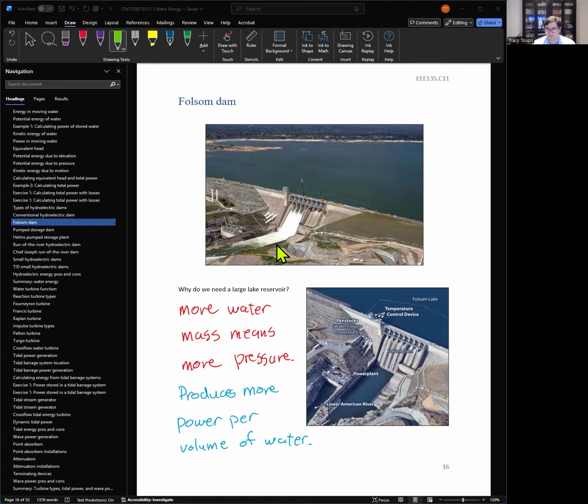Other thing you should note is the distance, the height. The after bay is down here, and the top of the dam is up here. So there's a pretty big 50-meter difference, I would say, right? That's a lot of potential energy behind the dam. Another thing to note is the width of the dam is not that long. The reason they installed it here is that it was a natural bowl shape of terrain. So all you had to do was build one wall here to encapsulate this whole area and turn it into the reservoir and lake.